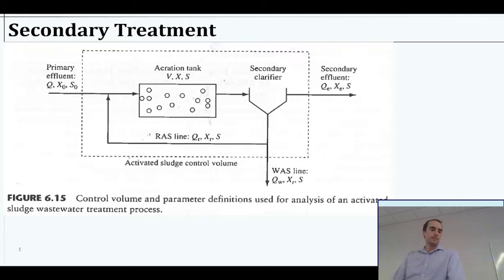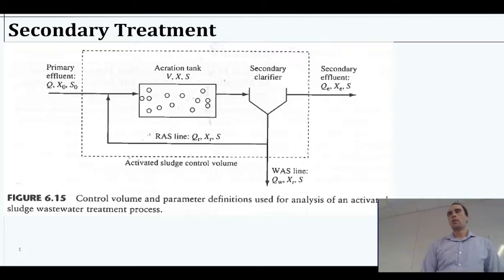Right. So last time we talked about wastewater, why we care about wastewater, all that stuff. Today we're going to talk about the secondary treatment component of wastewater treatment. This is after we've done a little bit of sedimentation and the generic basic screening of large stuff out of the water. Then we're going to use essentially biological activity as best we can. That's the whole goal of secondary treatment. Grow a bunch of microbes, catch them. It's easier to catch the microbes than the dissolved organic stuff.